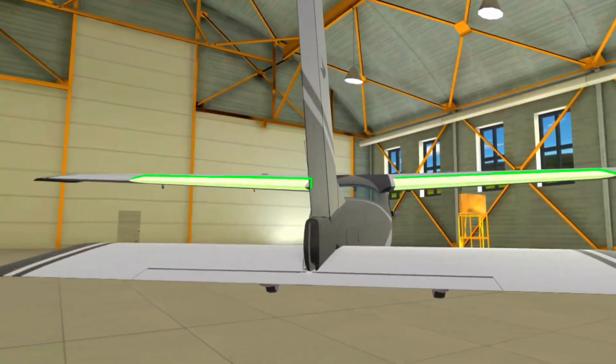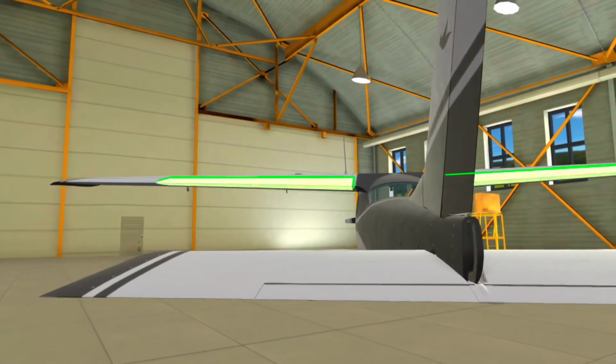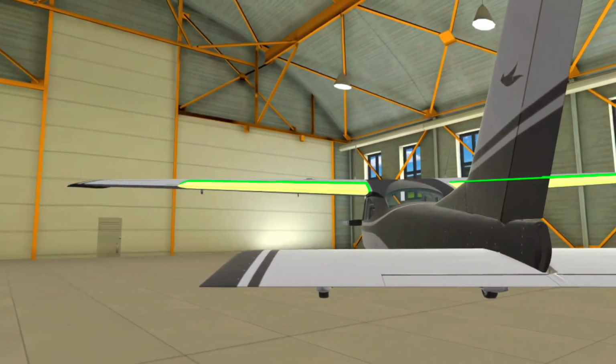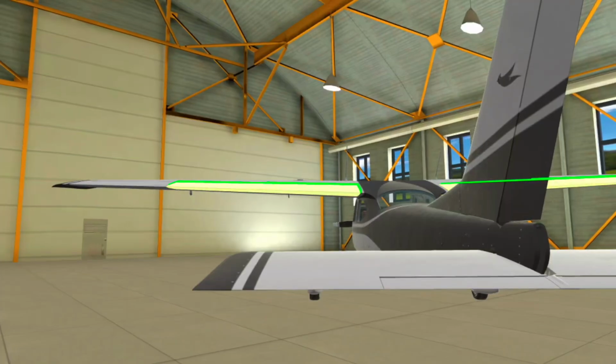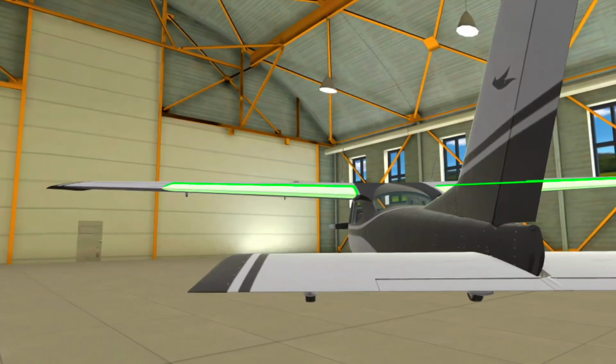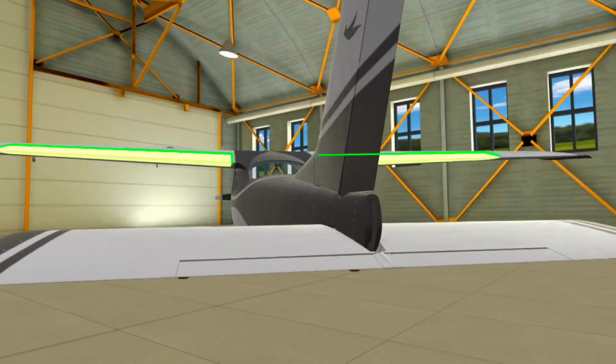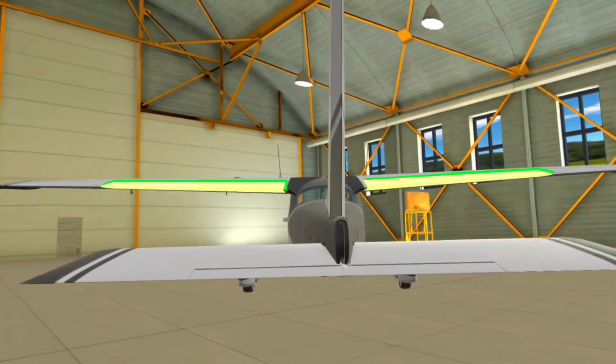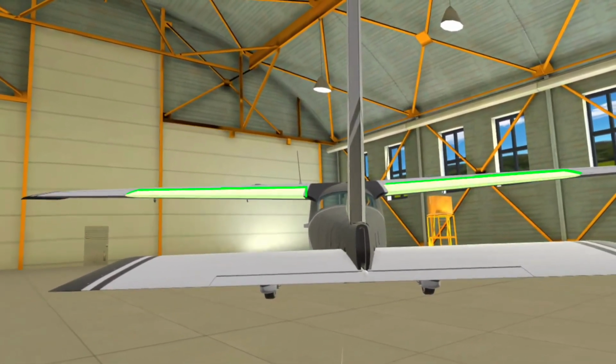The flaps are used to slow down the aircraft and generate more lift at lower speeds. These devices are mostly used during takeoff and landings. Flaps can only go down as opposed to the ailerons that move up and down. They can lower in steps of 10, 20 and 30 degrees. Flaps can only be used in a safe range of